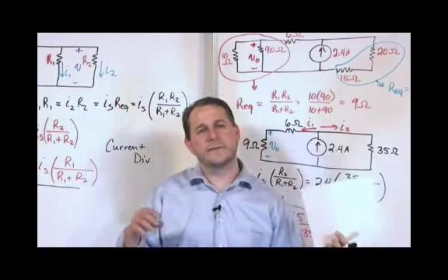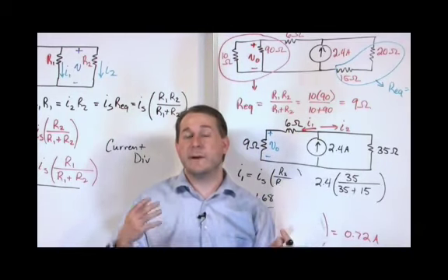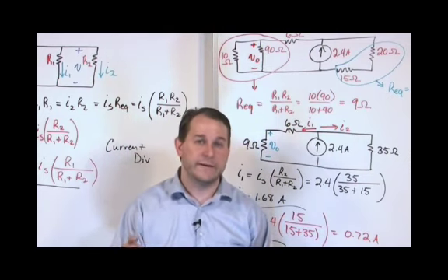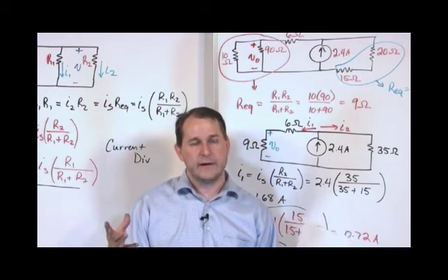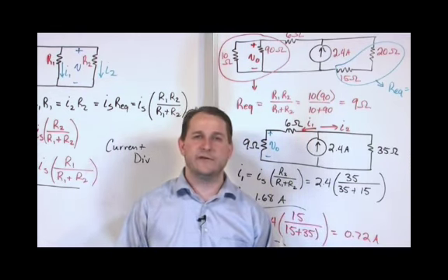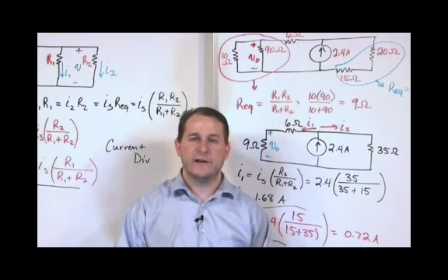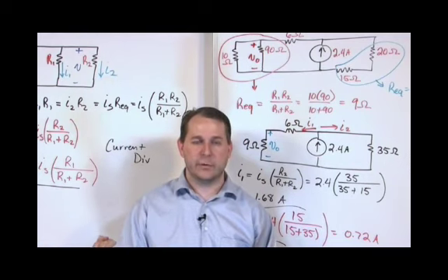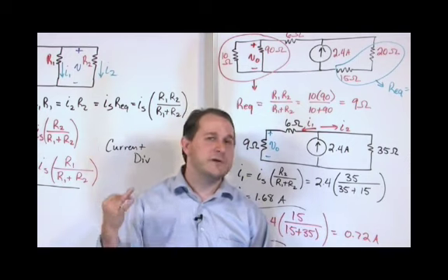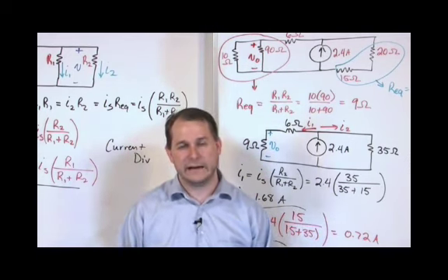We've learned about Kirchhoff's laws, Kirchhoff's current law and voltage law, and we've learned about power. Honestly, if I had to pick one of the most important things I've tried to get across in this course, it is the sign conventions. The sign conventions can fail you faster than anything, because if you don't understand them, you'll never be able to write a power equation correctly. You'll never be able to write a Kirchhoff current law equation correctly, and you'll never be able to write a voltage law equation correctly. And if you can't write those, you can't solve anything.